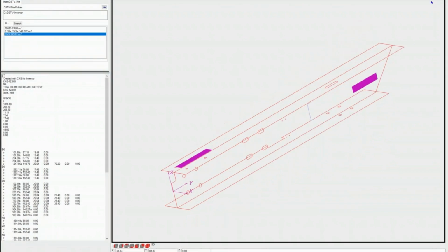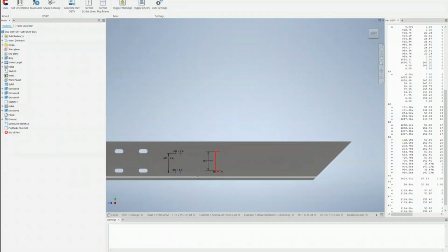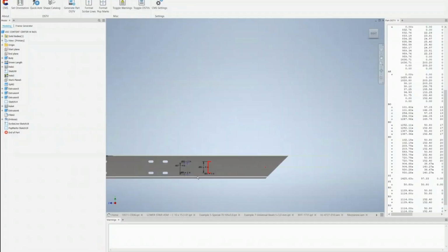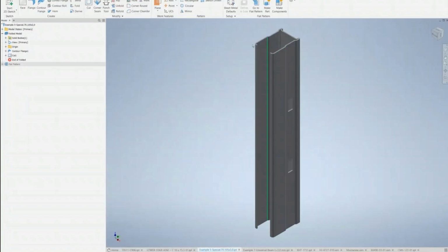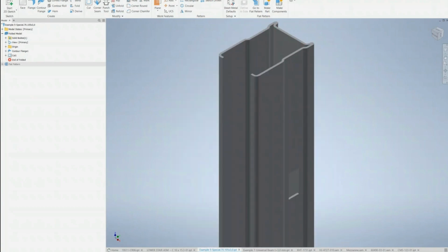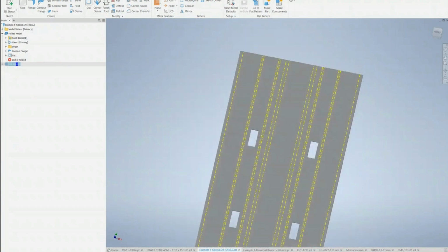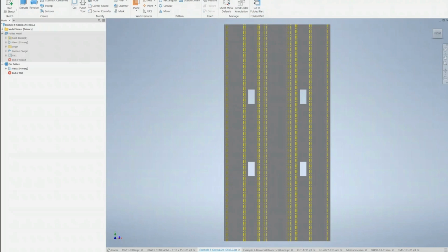Anyway, let's move on to our Inventor again. So now that we covered different types of profiles when it comes to single parts, I want to show you some of the functionalities on the sheet metals as well. As I told you, creating an NC1 file from sheet metal is very straightforward. All you have to make sure is that if you go to your flat pattern, it is actually on the XY plane. That's the only thing that you have to confirm.